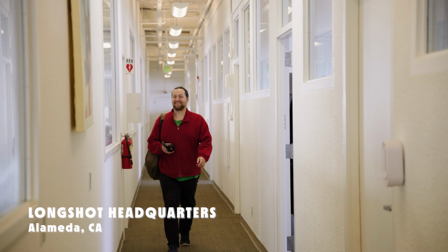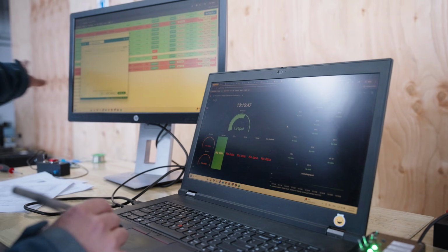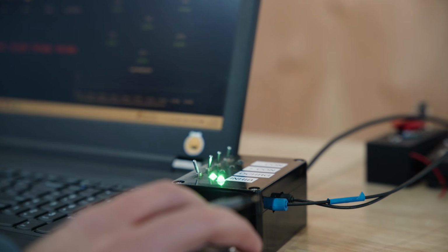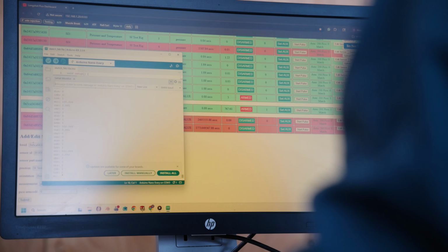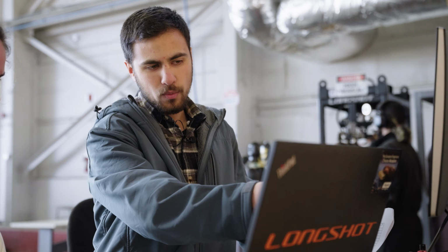The side injection test rig was a really exciting test rig to set up, just because most of the time in aerospace engineering, when you're dealing with hypersonic flow, it's a situation that takes place over a longer duration than what we're talking about here. In our case, we're not only dealing with hypersonic turbulent flow, but we're dealing with hypersonic turbulent flow in a microscopic timescale. I mean, these things happen in sub-millisecond timescales. So there's a lack of literature when it comes to actual data from this kind of setup. We are doing cutting edge technology in a shipping container. It's pretty fascinating to work on.